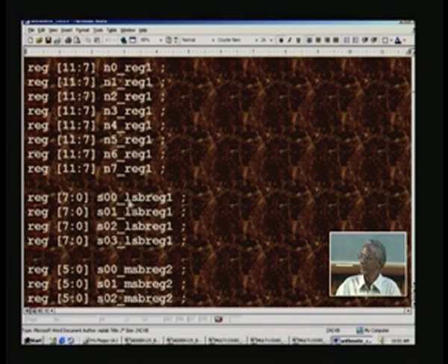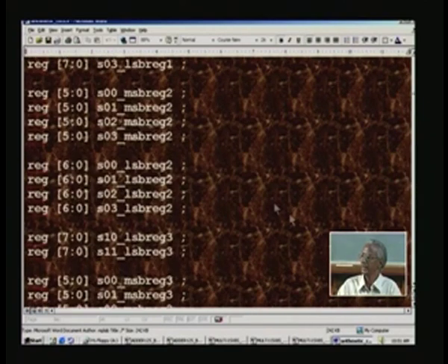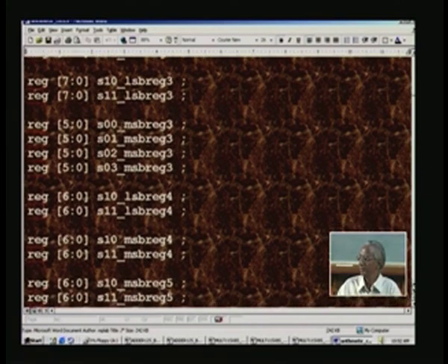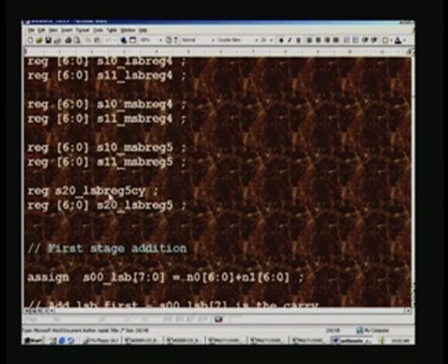And there are other similar next stage MSBs, LSBs listed here, and they are all declared as reg here, and so is the case here. This is the second stage, 1 stands for the second stage and 0 for the first stage. So once again you can see 1 0 second stage of MSB registers. And so this completes the reg wire declaration.